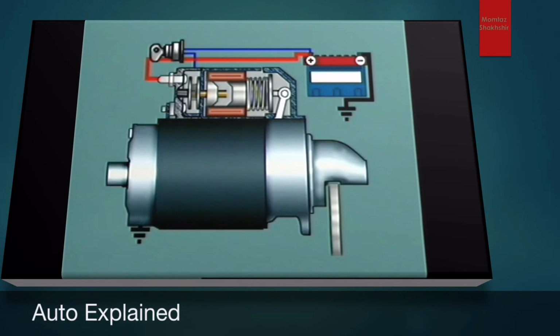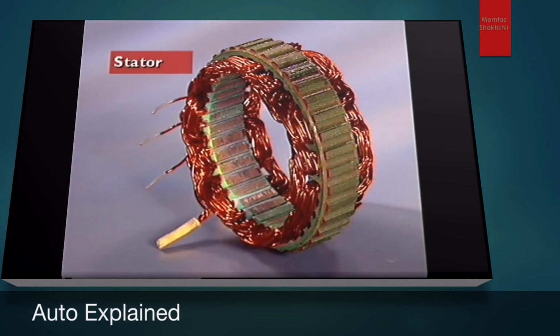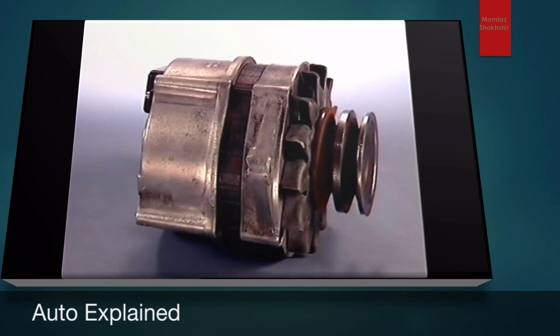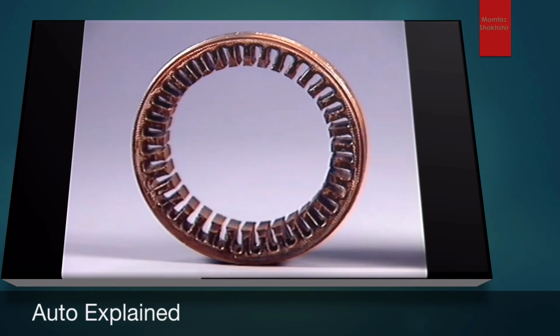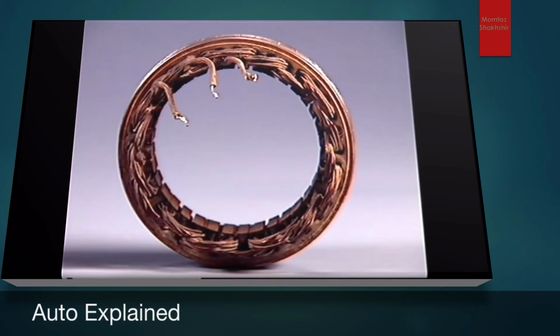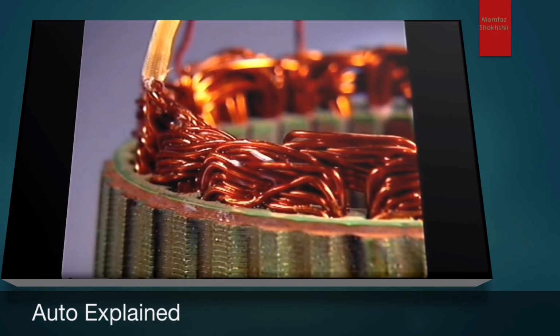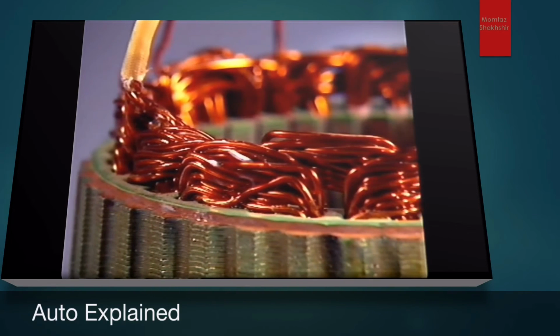This section examines the stator. The stator is mounted between the two end brackets. It consists of a cylindrical laminated iron core which carries the three-phase windings in slots on the inside. The windings are insulated from each other and also from the iron core. They form a large number of conductor loops which are each subjected to the rotating magnetic field.